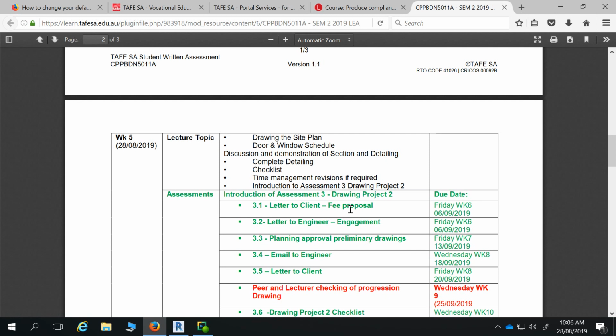There are also colours and paint finishes and all those sorts of things, because in a house you've got internal and external doors. They're going to have different finishes usually, so that adds detail for the contractors and for people to be able to tender. You don't necessarily need that detail for council, as long as they know the sizes of the doors, how much they open, etc. But you always need the window schedule to be a bit more detailed, and any doors that have got glazing on them. So you may as well do your window and door schedule, and then you can add that on now anyway.